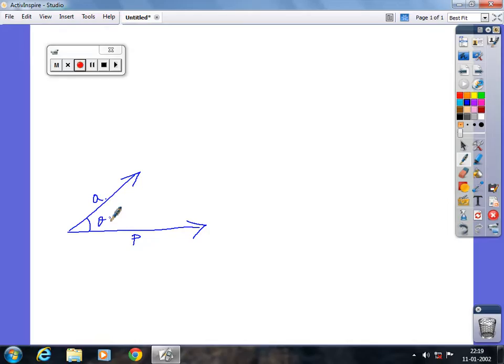All is wrong because this force acts in the horizontal direction and this one acts in the inclined direction, right? So you cannot say that the resultant here is equivalent to P plus Q or P minus Q. It's wrong. So there are three methods I said. One is the triangle law, which I taught you in yesterday's class. The second one is the parallelogram law of forces. That is also taught and you answered questions in connection with that. And the third one is the analytical method, right?